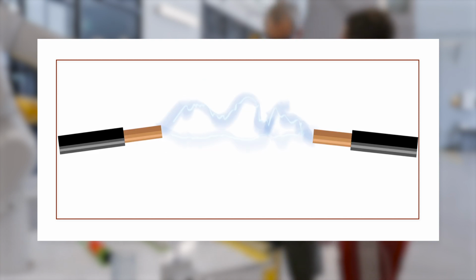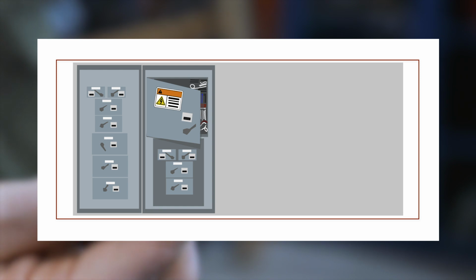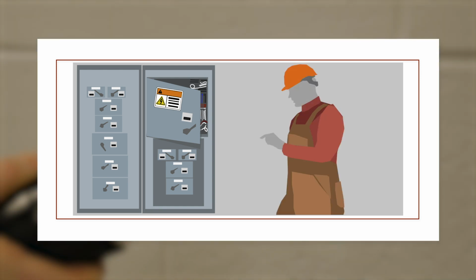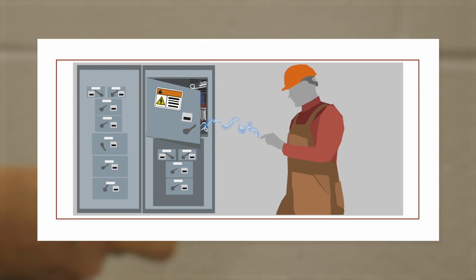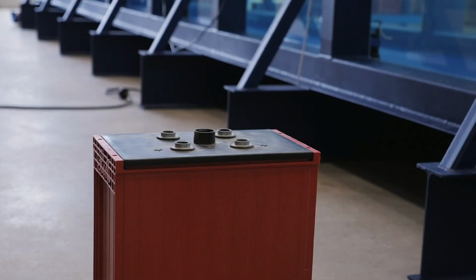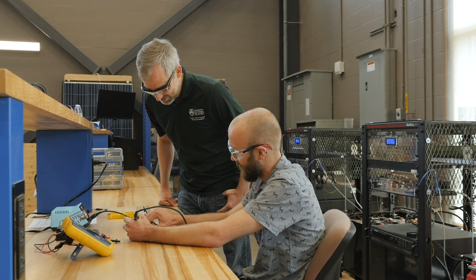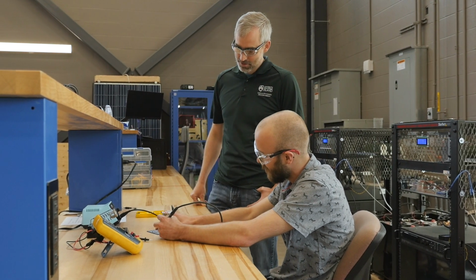Electric arc is a potential hazard that can occur when high voltage sources release energy through the air. It is typically caused when a conductor, such as a metal or the human body, is brought near a high voltage source or conductor. An electric arc can cause blindness and fatal burns at distances of over 10 feet away. Avoid placing or carrying conductors near other live sources, and always talk to a technician before working with sources above 24 V.